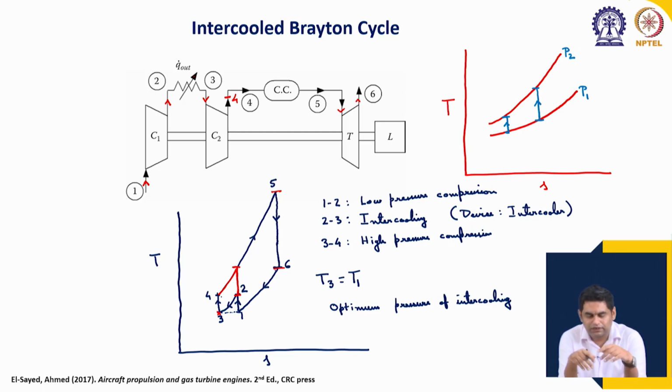On the other hand, this heat exchanger addition for intercooling is both bulky as well as it makes the cycle not self sufficient. So, you now need a continuous supply of water to run the cycle, unlike the previous cases. This makes the cycle depend on an external supply of water.